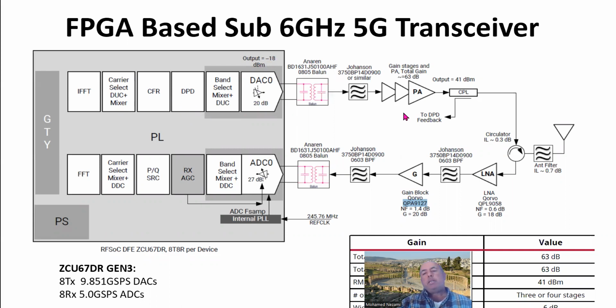So you go from minus 18 to 40 dBm, which means you have about 60 dB of gain to implement between the antenna and the DAC, including, of course, the transition from balanced to unbalanced, or single-ended. All these components are off the shelf, and I will demo a model of a chain like this in SystemVue PathWave shortly or in the next session.